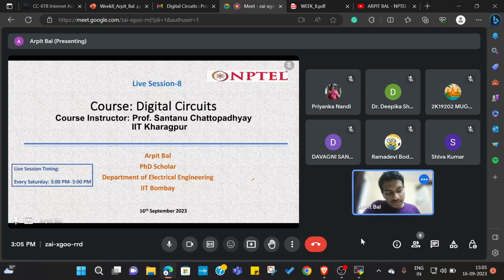Now let me summarize a few lines about the data converters. They basically form an interface between your analog and digital world. And why exactly are we talking about analog when we are hearing about the digital revolution everywhere, right? But the digital revolution is not possible without analog. The world is analog, and at the heart of this digital revolution is actually analog electronics. So to get the data into digital form, we need an ADC, and to get back a understandable representation of the digitally processed data, we need a DAC, that will convert the digital signal into an analog signal.